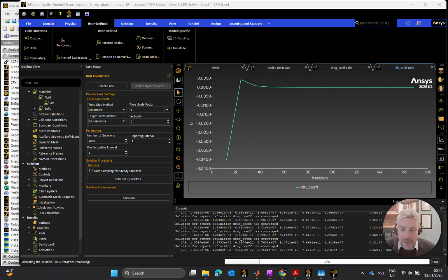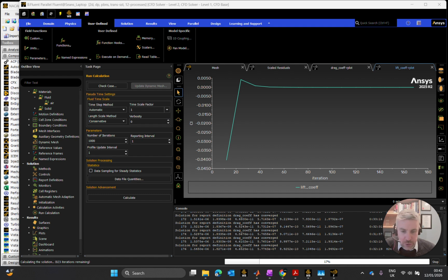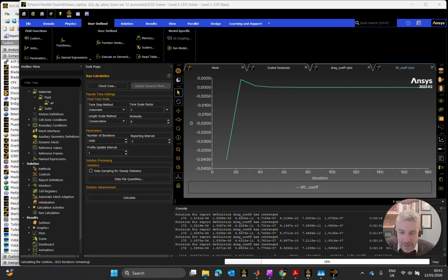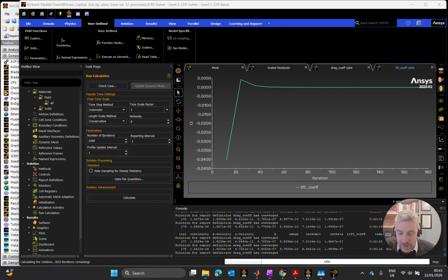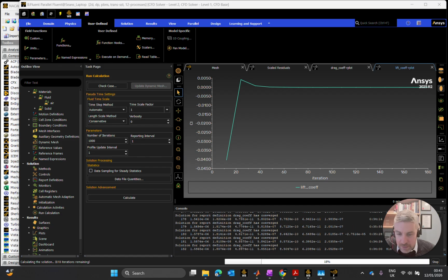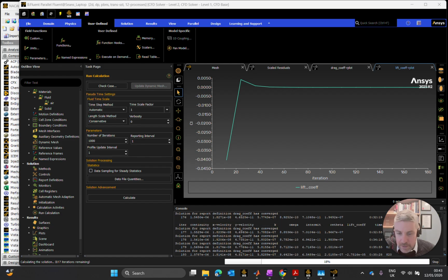Okay, I'm going to come back, and what I'm going to do is stop this here, because I'm not going to let it run out to 1,000 iterations. I'm satisfied that it's converged adequately enough. I was maybe overambitious with my targets, especially for the continuity. As you see, it did come down fairly low, and now it's just starting to go up a wee bit. So it did come down there as low as 1.4.